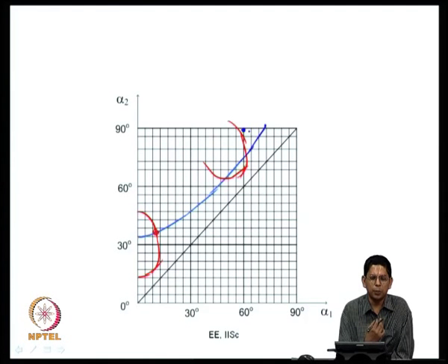At that point the waveform could be a ninth harmonic square wave, or a third harmonic square wave itself. For 3 switching angles you will not get a ninth harmonic square wave, but you will get a third harmonic square wave. So, that could be a good point to start your solutions many a times, because that point naturally satisfies the Vn is equal to 0 equation now.